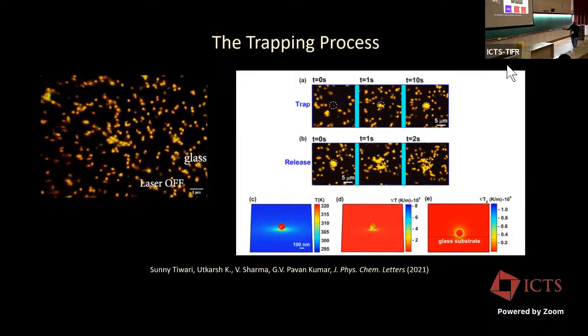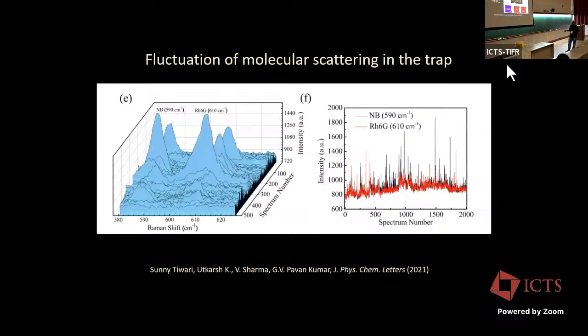You will also be able to generate this purely because of the fact that you are now creating a gradient of temperature around an illuminated gold particle, which is laid on a glass surface. So this is a 3-dimensional heat transfer equation, which has been solved, and you will be able to map the gradients of temperature along the z-axis and also the other two dimensions.